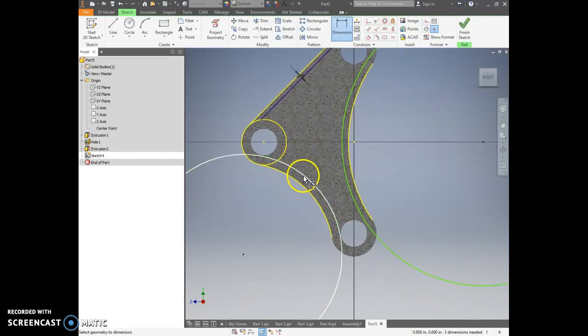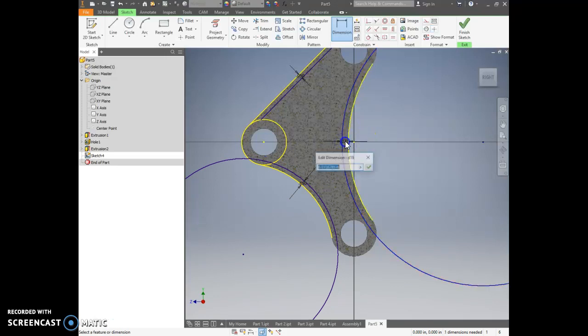Now, sometimes it'll let you do this, sometimes it won't. So sometimes you can go between those two, and there it did let me do it, and set that to 0.05, and then set that one there to 0.05. If it doesn't let you do that, you just have to add 0.05 onto this radius you had before. So it was 1.5 radius for this circle. You'd have to change that to a 1.55 radius. Hopefully that makes sense. So there, those lines all laid out perfectly into place.